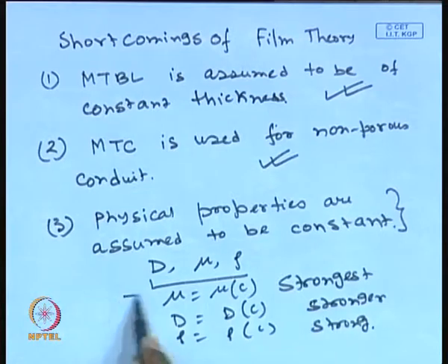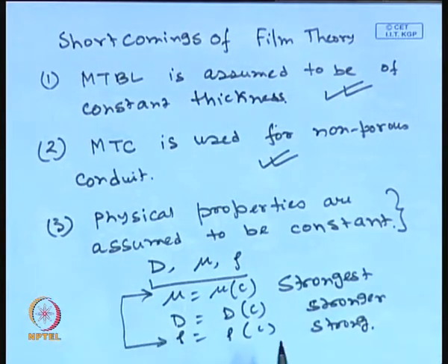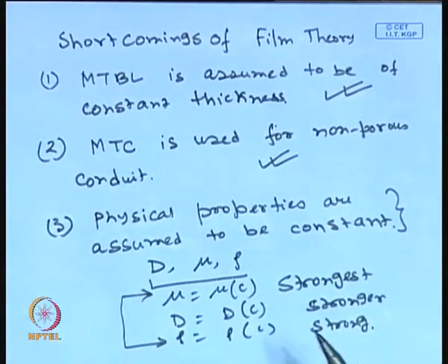Now, we have already talked about the osmotic pressure control model, and we have already talked about the gel layer control model. In the osmotic pressure control model, the membrane surface concentration will be maximum around 10 times the feed concentration, and in most cases it will be 3 to 4 times the feed concentration. On the other hand, in gel layer control filtration, the gel concentration, that is the wall concentration on the membrane surface, becomes sometimes very, very high. It becomes 40 times the feed concentration, sometimes 50 times the feed concentration, and so on.